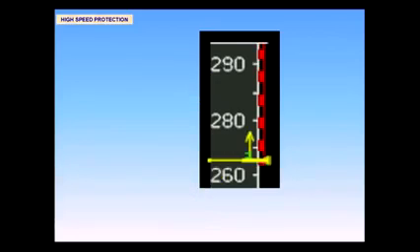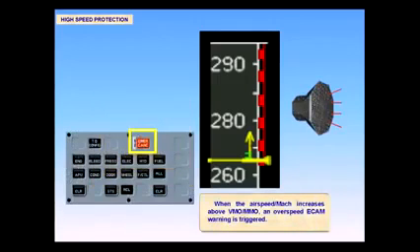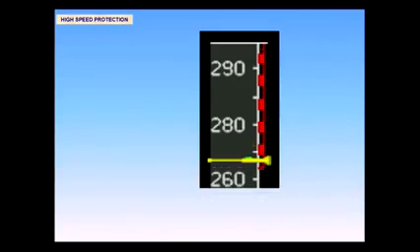When the airspeed or Mach increases above VMO/MMO, an overspeed ECAM warning is triggered. If the airspeed or Mach increases to the protection speed, the autopilot will disengage and the flight control computers send a pitch-up command to the control surfaces to prevent further acceleration. The flight control computers will permit momentary exceedance of this speed for maneuvering if necessary, but will then return to the protection speed.